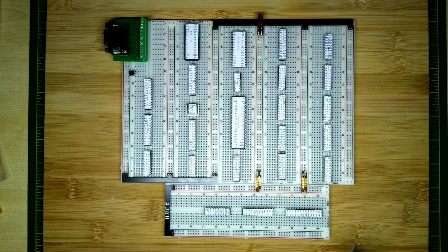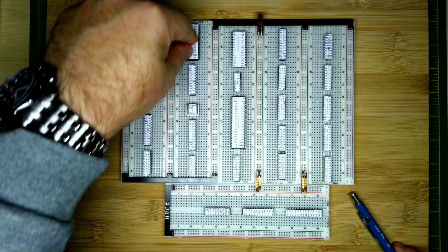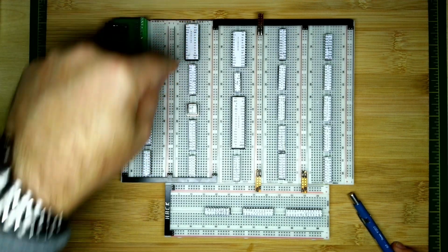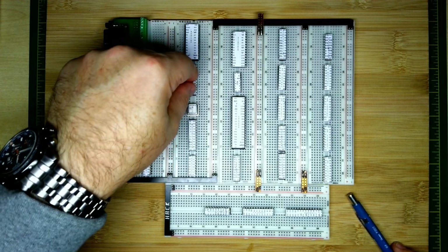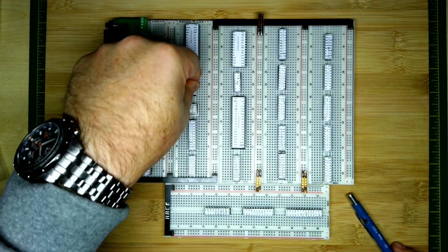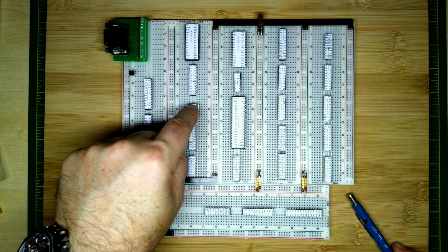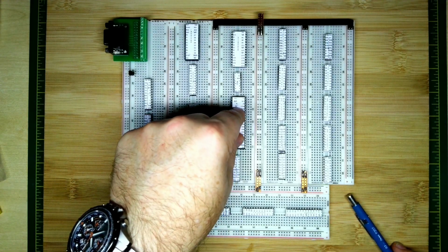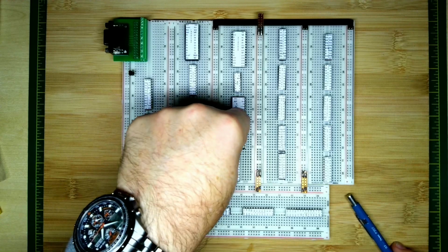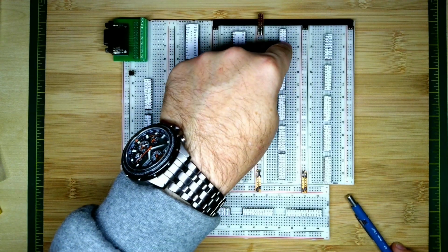So the chips are going to need to wire up. First of all, we've got the digital analog converter, so I'll just plug that in. We've also got the clock PLD, so we're going to need to have the CGA clock PLD. This is the 25 megahertz dot clock crystal. We've got the CRTC here. This is the IO decoder over here.